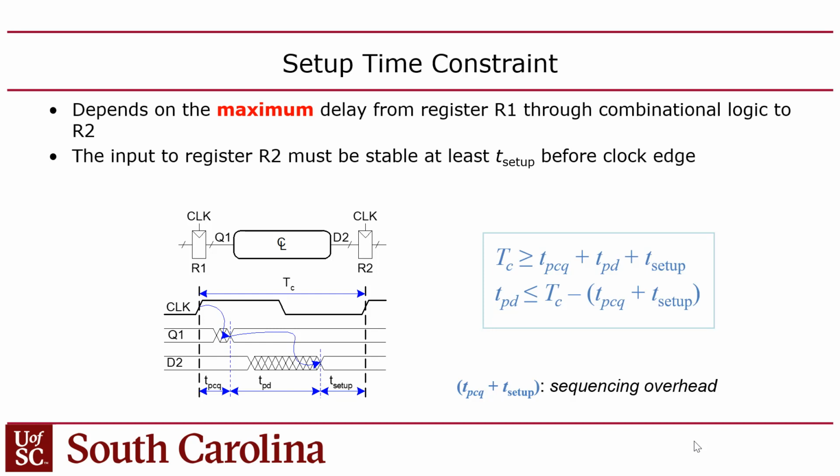So in our CPU, we have a long stage. We have that execute stage, right? It requires you to read the registers and go through the ALU, all in one cycle. It may be the case that results in a propagation delay that's just too high. In which case, we may have to break our CPU down into, say, 4 stages or 5 stages. We may have to break that up, right?